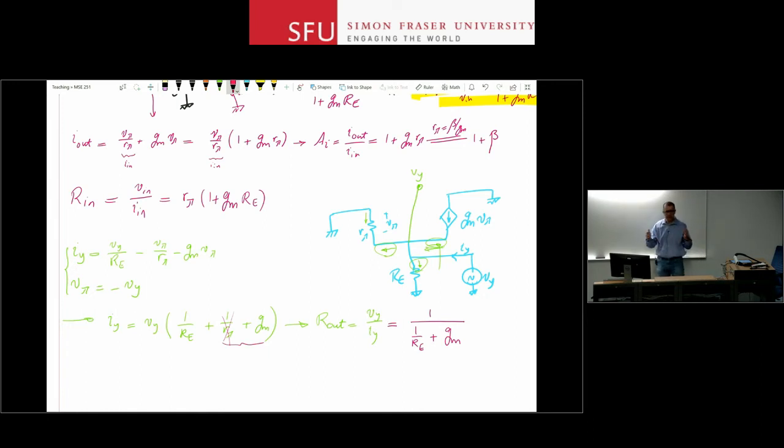Is it big? Is it small? It's hard to say. So let's do one modification. Gm is transconductance. The unit for Gm is current over voltage, or Siemens, right? So let's define a resistor that is 1 over Gm. GM is amps over volts. I flip it over, it will become volts over amps or ohms.